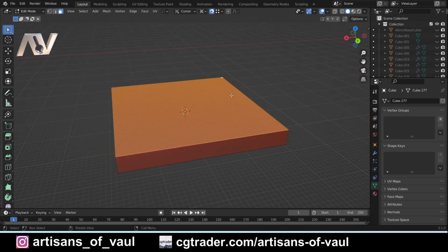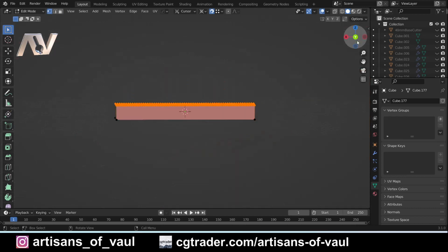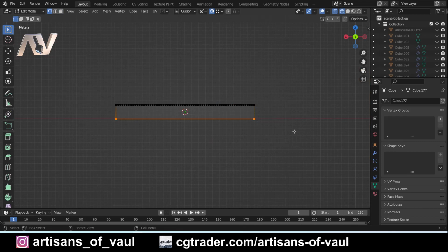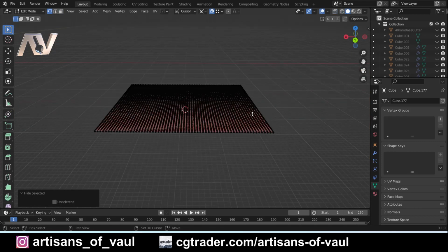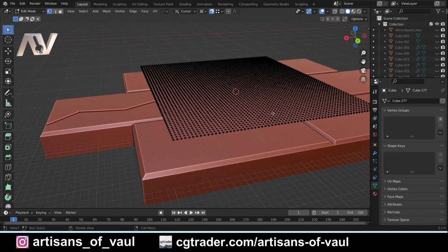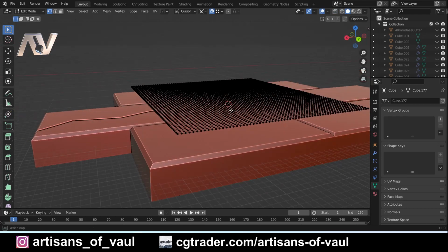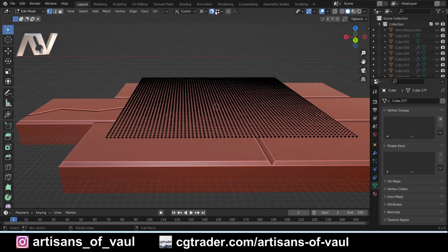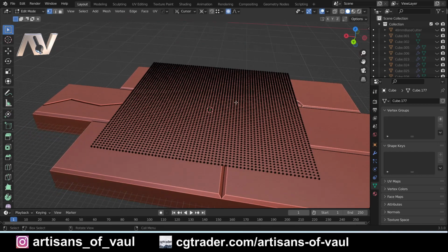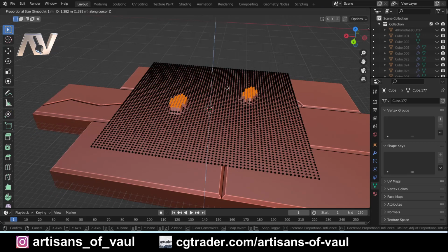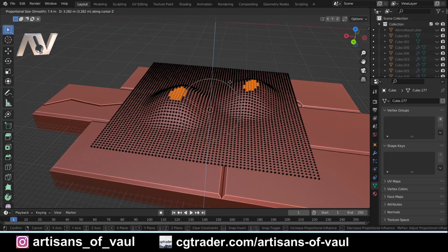And finally I'm going to go into isolation mode, go into vertex mode, Shift and Z, and I'm going to select the bottom vertices. I'm going to hide them so they're not being affected as I start doing things to the top. And I've now brought that out of isolation mode. I think I had snapping on for something there, and I'm just going to select some of those vertices, for example here and here, and I'm going to G and Z those up using proportional editing to make that into a sort of couple of mounds there.